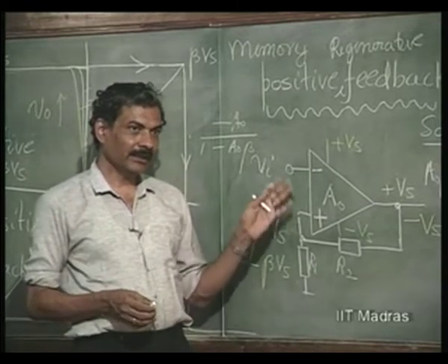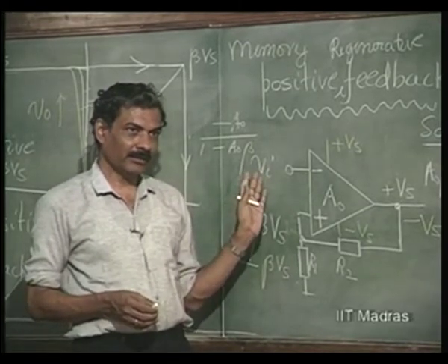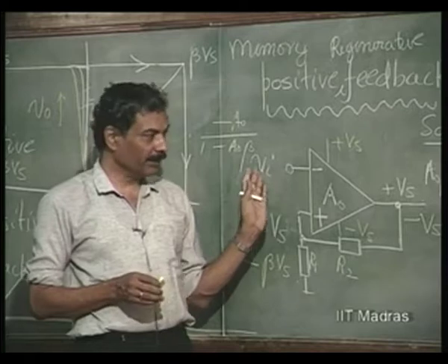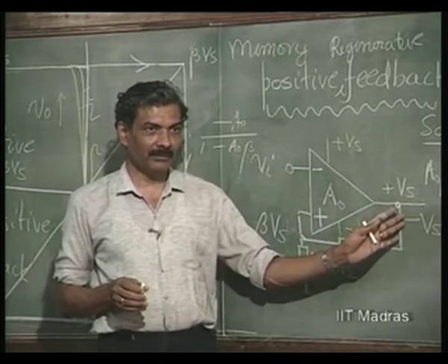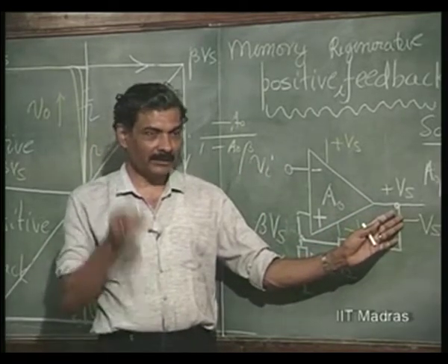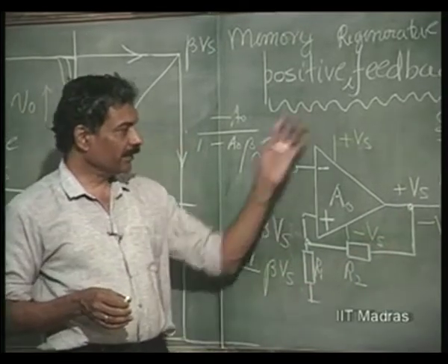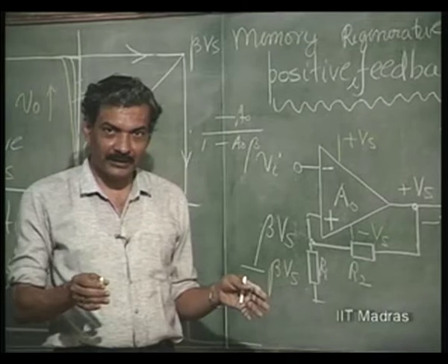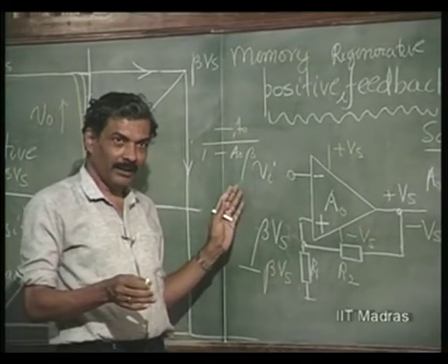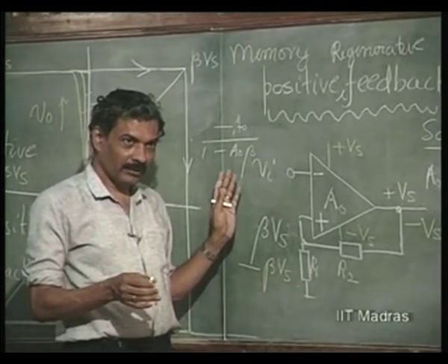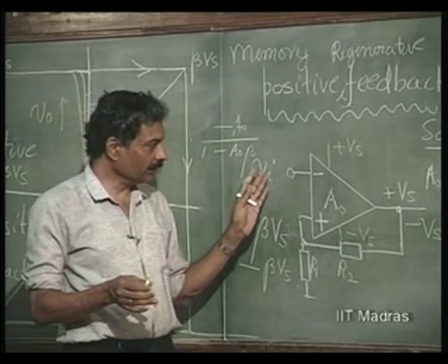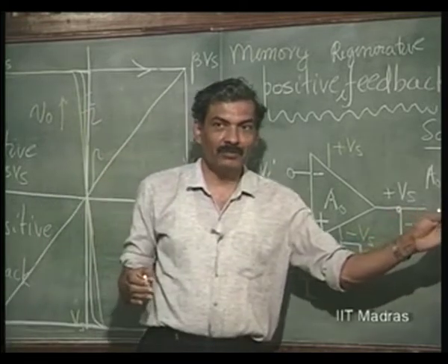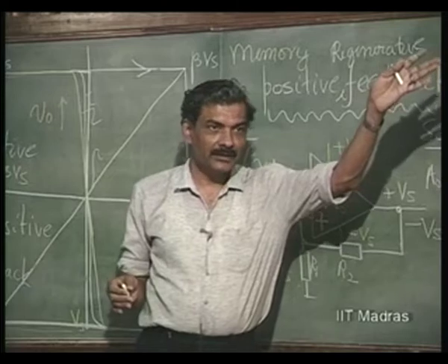So, for converting pulses which are out of shape into pulses with sharp edges, the Schmitt trigger is always used. So, this is the entry point into a circuit. All the data transmitted pulses should come through a Schmitt trigger before they are processed further in any circuit.